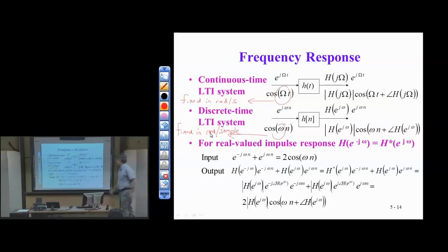For one, in theory, this also works for a one-sided cosine, and it also works for a cosine that's observed for a finite period of time. All right, so back to the theory. We have a two-sided cosine. What this means is that I can put in a cosine at, say, pi over 2 radians per sample and look at the output. I can put an input in at, say, cosine pi over 4, pi over 8, 3 pi over 4.